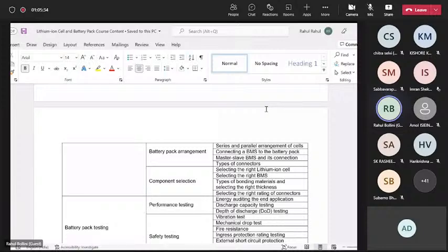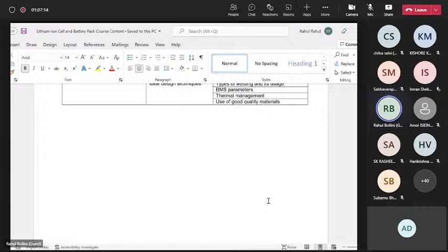What is the difference between them, and where you need to use what cell grading, because just some time ago someone was telling about the cell balancing issue. So if your grading is good, those issues will never happen. So firstly, it's a continuous process where the heat dissipation has to be good. The BMS has to make sure that the battery pack is operating in the limitations of the characteristics of the cells, and you need to use high quality cells. So these are something which Indian OEMs are failing. And let me quickly come down to BMS and VTMS course.